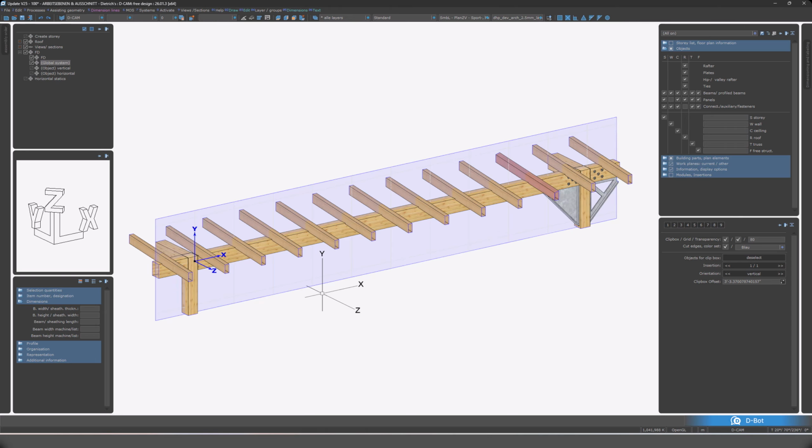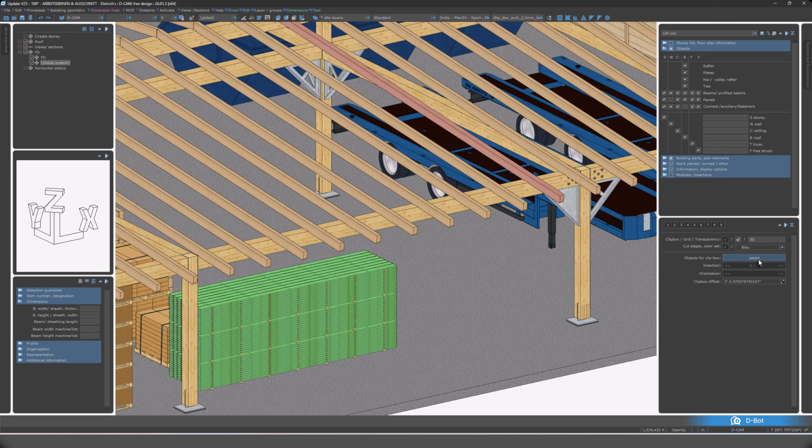And you can now see that it has created 2 other work planes, we have a vertical one and a horizontal one, and we can click through them down here as well. With the column that we just had in the previous example, we had two different work planes, essentially two vertical ones, but in two different directions. Now we have vertical and horizontal. I'm going to now deselect that again.